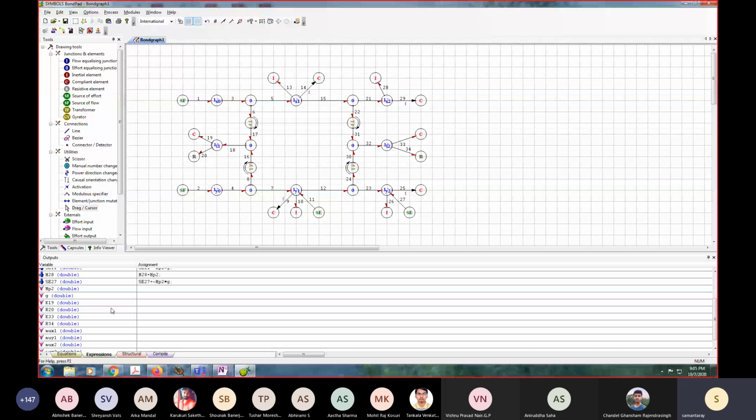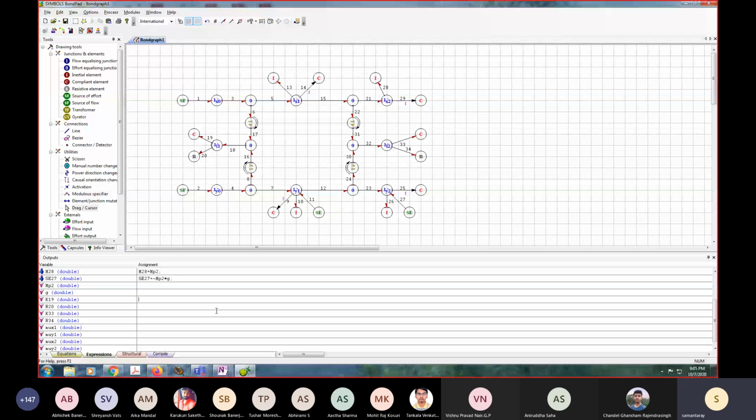All right. Now I have K19. This K19 is stiffness of rod 1. So what will I write? A star E by L1. L1 is a new variable created, AE is created. R20 is lambda star K19.